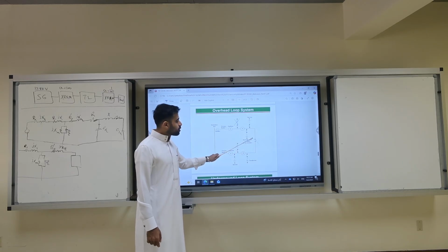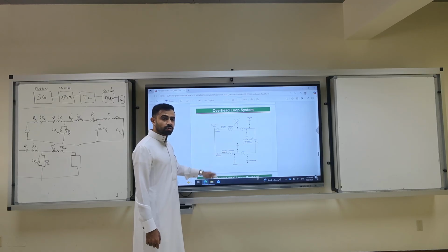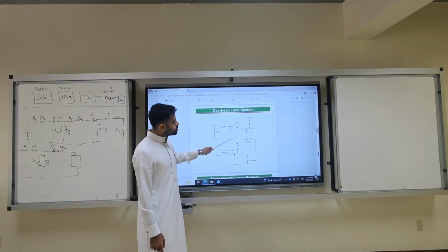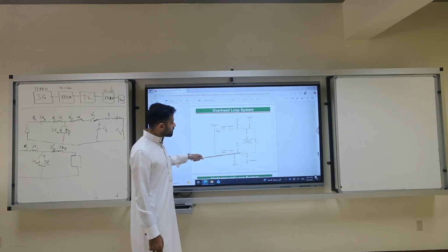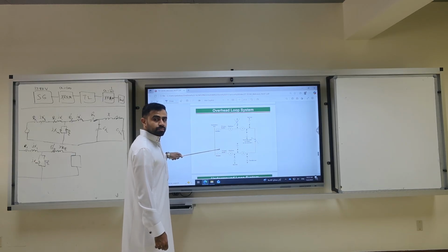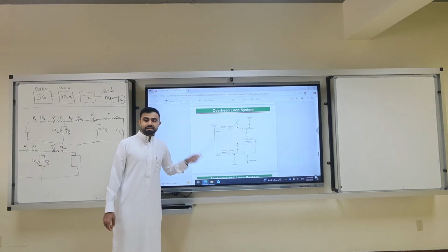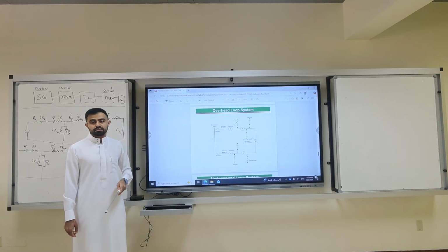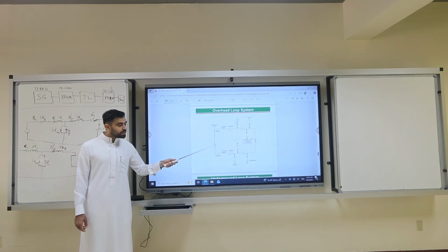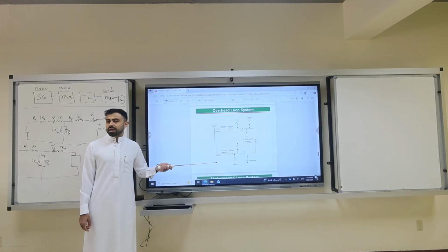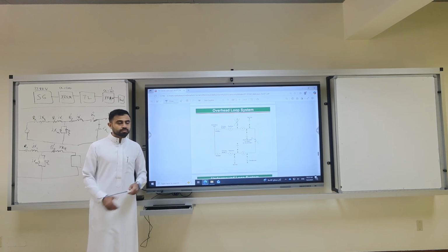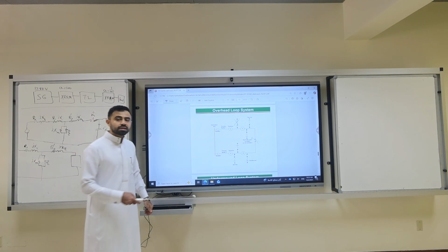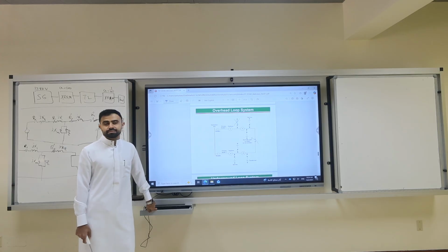So the center would close the normally open switch. We call it tie switch. And we tie these two loads to the feeder number 2. We'll ask you in the exam, explain. Okay? It's very fundamental. Very few electrical engineers know the difference between radial and loop. In the old 360, they never taught them these things.